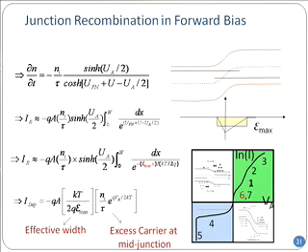In the high current part, what is the signature of? That is the ambipolar part, right? Ambipolar has lots of electrons and holes together. That's where the 2 comes from. That's high current. But at low current, if you also see half the slope, then you know that's because there's a lot of traps in your system.